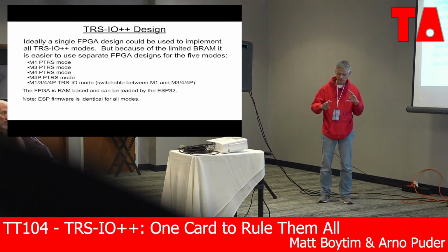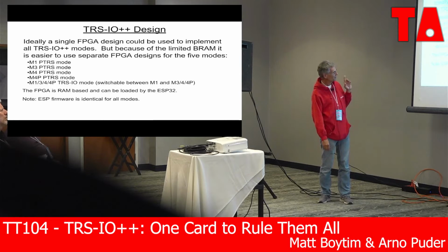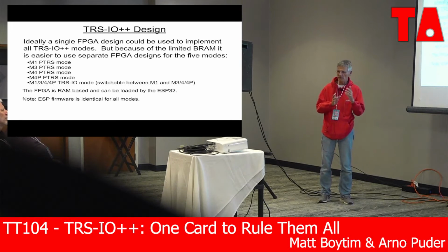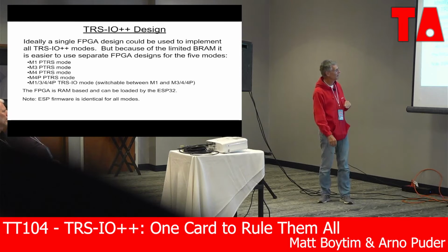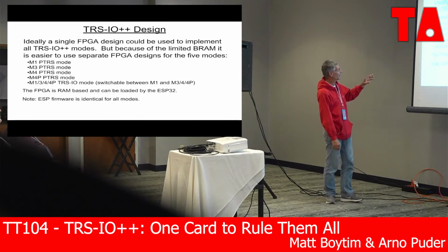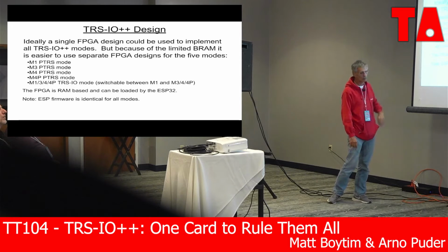If you have enough resources, you just switch things in and out. In this case, in order to do it, we would have to move the BRAMs around, which becomes very difficult because here it might be a 14K ROM. If we want to switch to a different mode, we have to break it in half, and 10K goes here, 4K goes here, and that becomes rather tricky and clumsy. So I just decided we're just going to do multiple modes of operation.